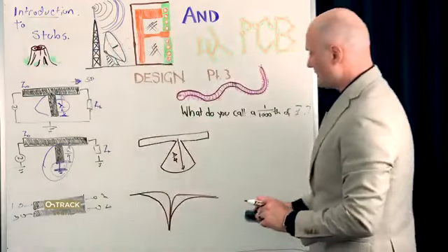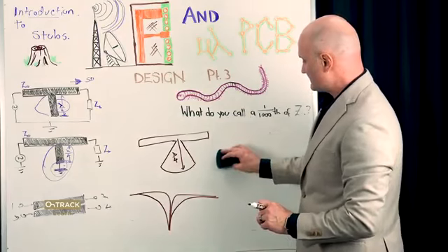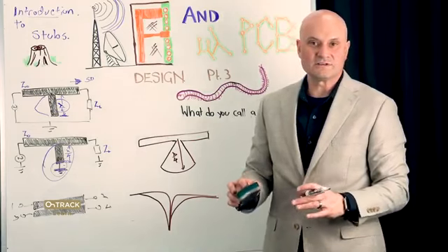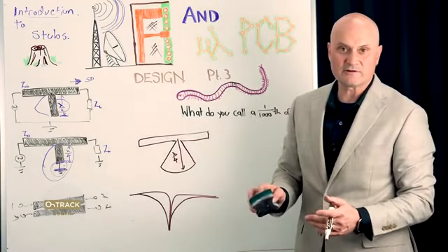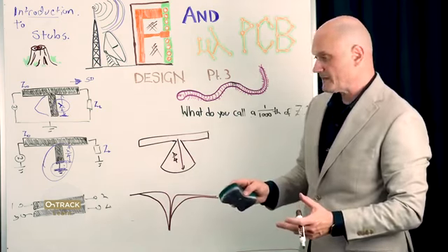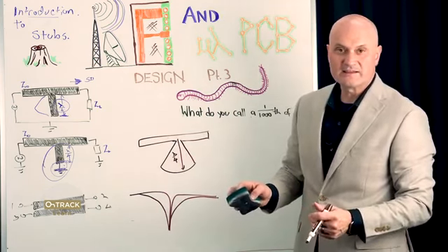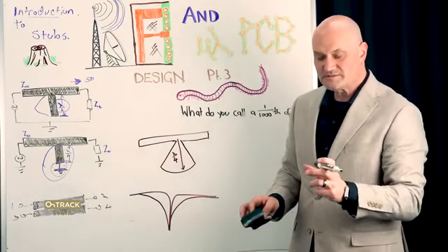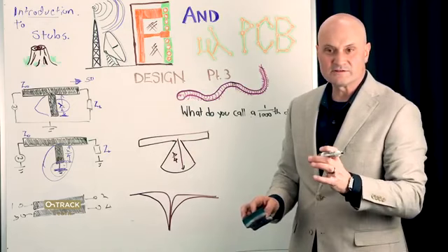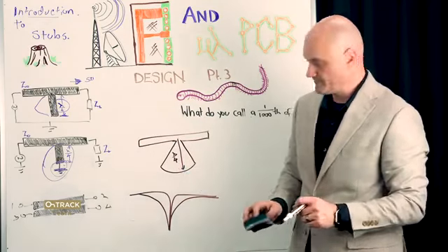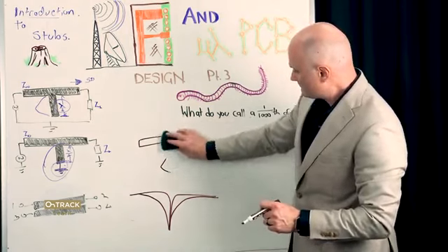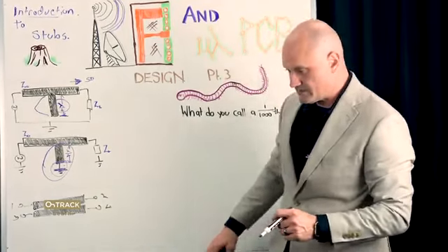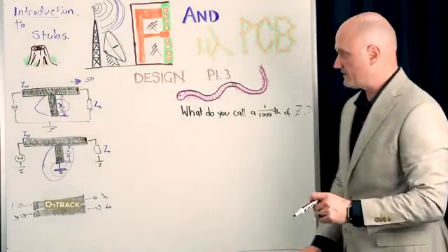There's no exact science or closed formula, unfortunately, for radial stubs. Almost always they're designed by intuition, and they can be modeled in software, but they require some numerical modeling techniques where each stub is divided up into tiny short transmission line segments of different widths, and then those are modeled together as if they're all in series. But most tools out there and simulators know how to do that, so that makes it much easier for us, and we can still get a good starting point before we cut metal.